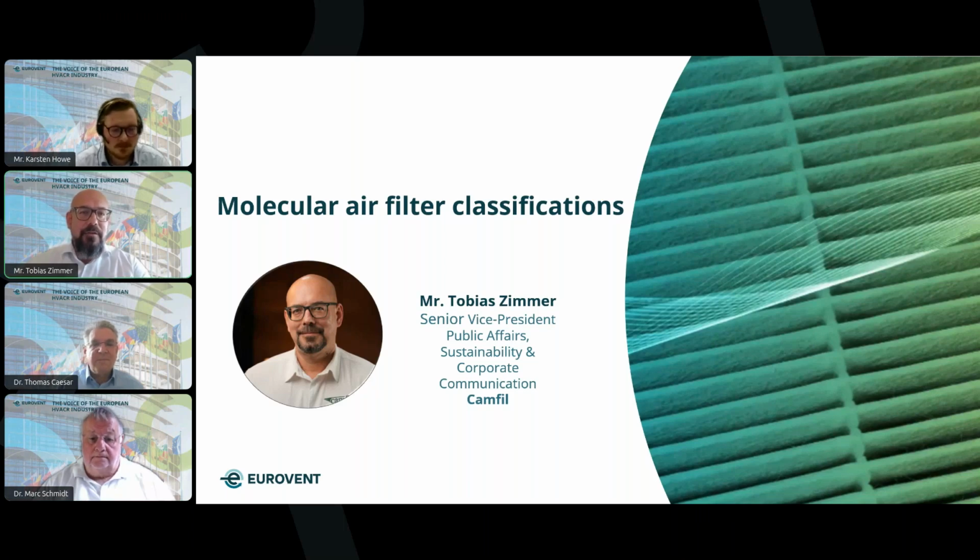And some of you may remember that in the past, there was basically no classification for carbon filters whatsoever. It was kind of black magic. So some expert had to tell you, does it work or does it not work? Which was not easy to dimension, especially when we're talking about a regular supply air comfort application. But the good thing is that has changed some years ago, and this is one of the main parts that is addressed in the Eurovent 426.